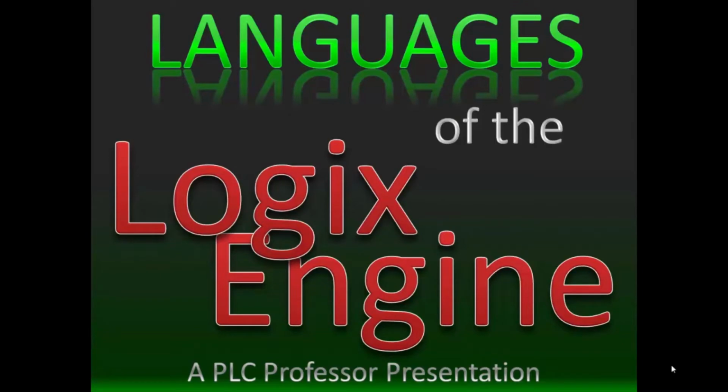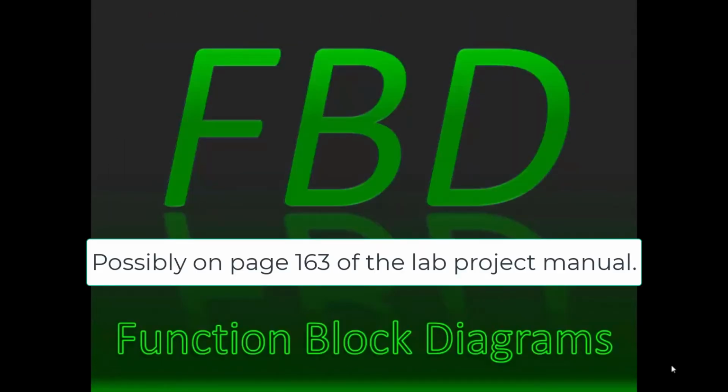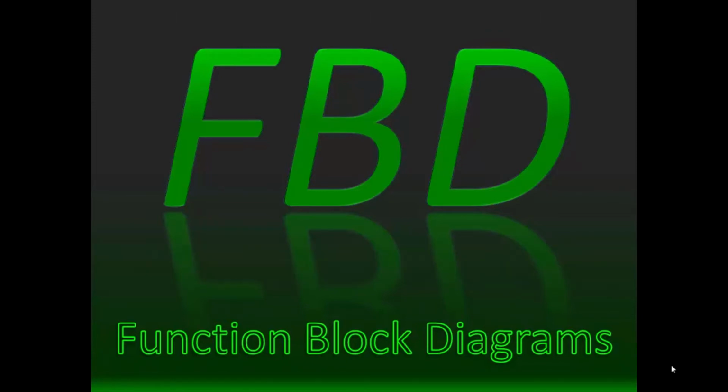Ladder logic diagrams, function block diagrams, structured text, and sequential function charts. This one is on function block diagrams, FBDs. This is one of the more fun languages to use because it flows the information a little smoother. When you look at ladder logic diagrams, you have to read quite a bit before you get the gist, before you get the essence of the process. But with function block diagrams, it's very easy to see the process. That's what makes these so popular.